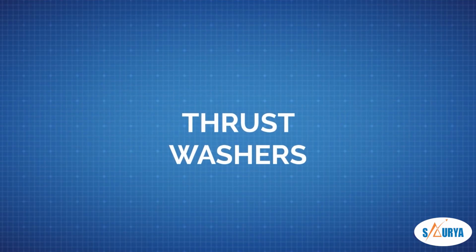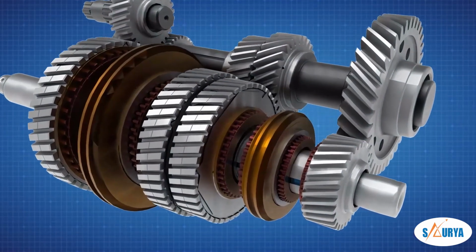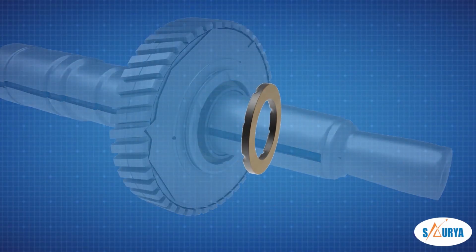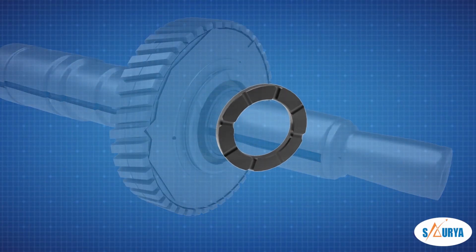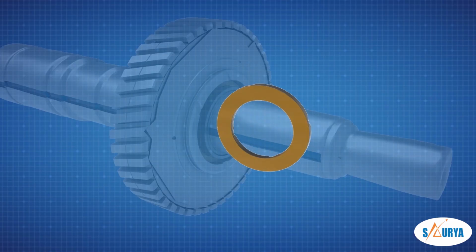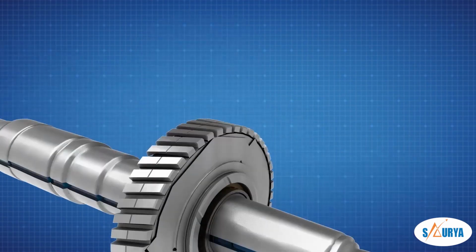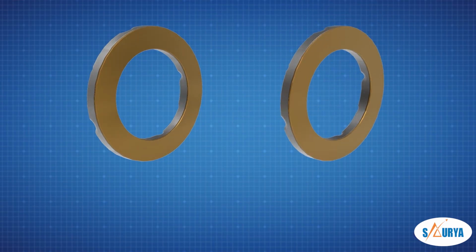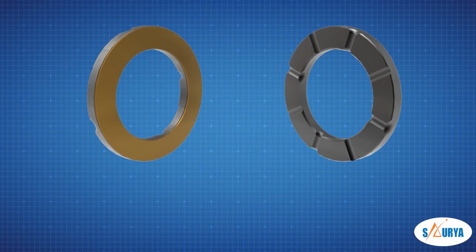Thrust washers. It's fitted with roller bearings. Thrust bearings or washers are used to limit the end play and also reduce the friction between two rotating parts. Roller bearings are used in combination with flat thrust washers to control end play of a shaft or the gap between a gear and its drum.